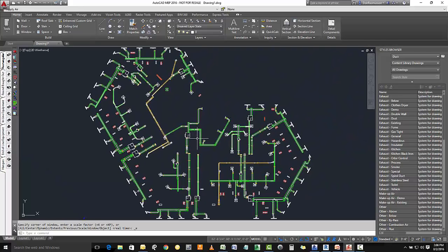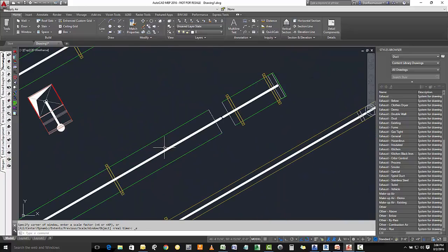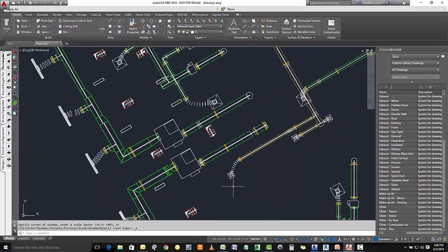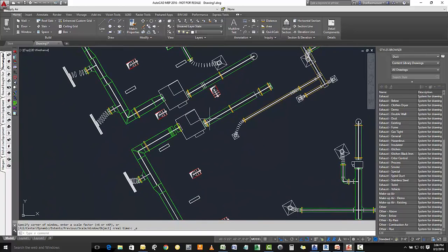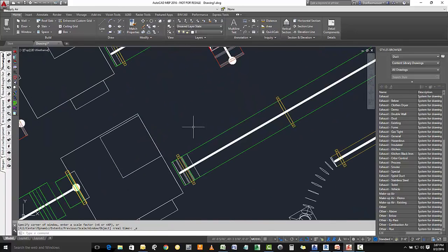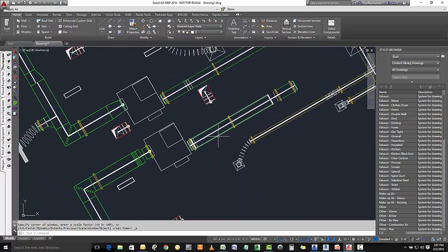And there we have our export. Now this is that RIF file again that came in, and basically what it does is it creates a design line, and this design line basically populates based upon three things: the route of the line, and then the size of the duct, and then whether it's rectangular or round. That's really all it's looking at as far as populating this with parts.